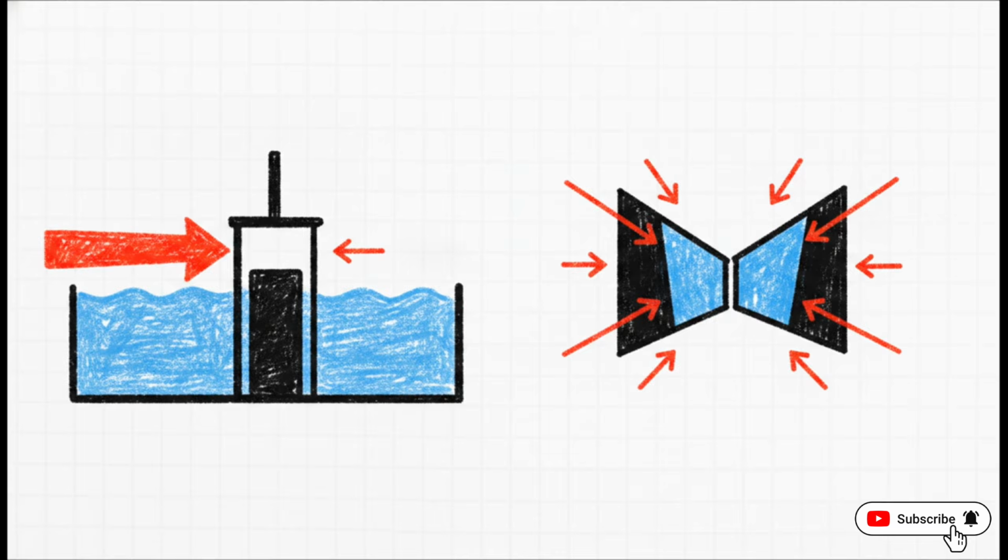For a sluice gate, you usually have water on both sides, so the total force, F, is simply the massive upstream pressure, F1, minus the downstream pressure, F2. Engineers just have to ensure the gate's tracks can handle that difference without buckling. But for lock gates, it gets even cooler. The two doors meet in the middle at an angle. The formula P equals F over 2 sine theta calculates the exact reaction force at the hinges. Because the doors meet at an angle, the massive pressure of the water actually compresses the doors into each other and into the hinge. It's literally using the water's own crushing force to keep the doors tightly sealed. It's honestly a genius application of fluid mechanics to prevent catastrophic failure.